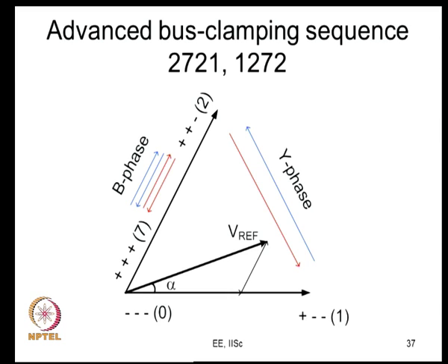You can see that in a half carrier cycle a phase can switch only once in triangle comparison based PWM, because it can only intersect once, whereas here you can see it is switching twice. So, this is a benefit that we are getting, we are able to divide an active vector time. This active vector is applied twice, which is not possible normally in methods like sine triangle PWM, where an active state will be applied only once. So, the only option is between the two 0 states, either both will be applied or one will be applied. If both are applied, again one may be applied for 0.8 Tz, the other for 0.2 Tz or whatever. So, there the only degree of freedom is division of null vector time between the two 0 states. Here you have that freedom.